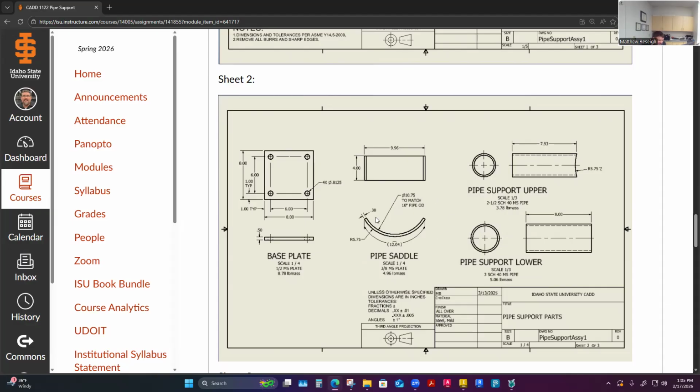But some of these dimensions I view as mostly reference dimensions. I could put parentheses around this 3/8 really if I thought about it, but it gives them a rough idea of maybe how wide that'll finish when they've got it rolled to the right radius. So why I'm doing this is, let me show you how I put these dimensions on there.